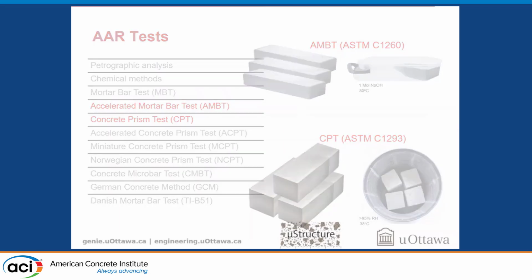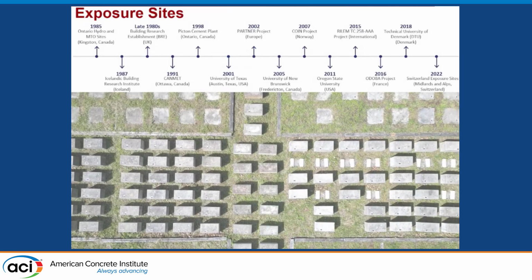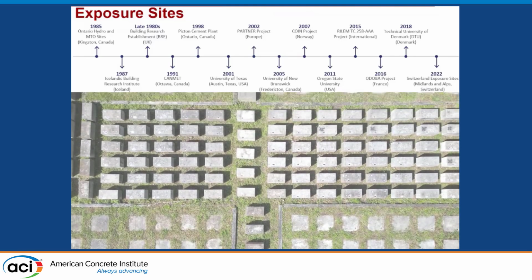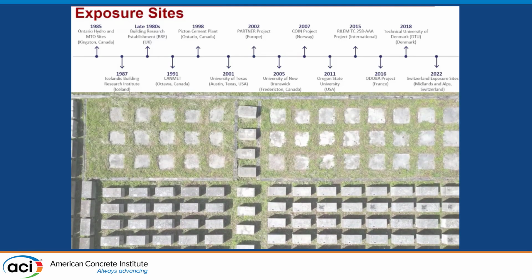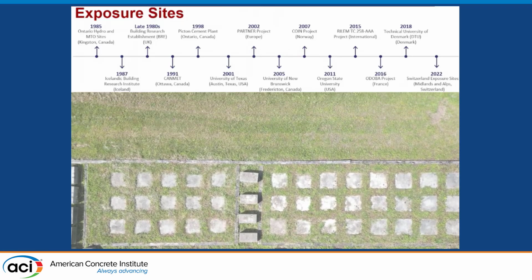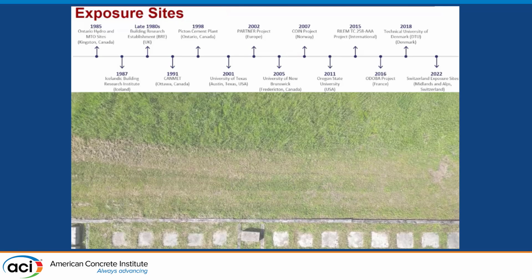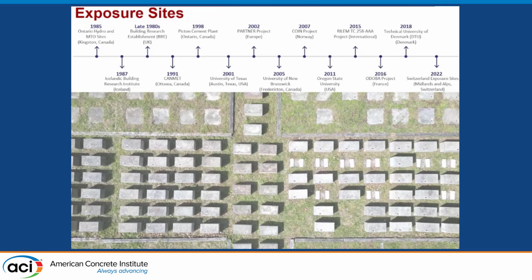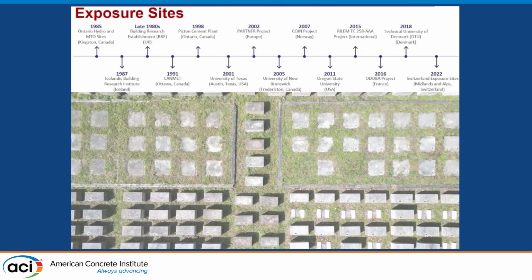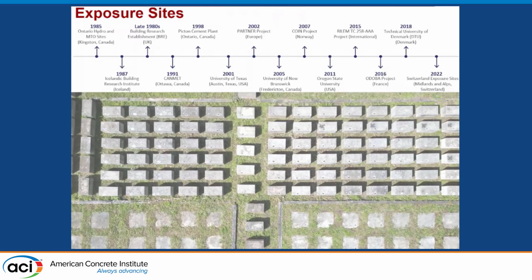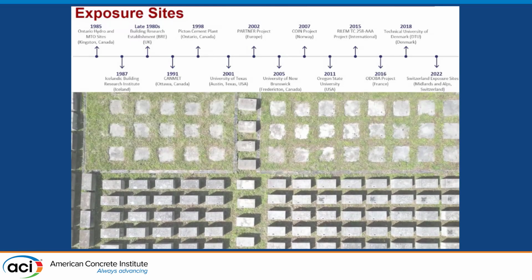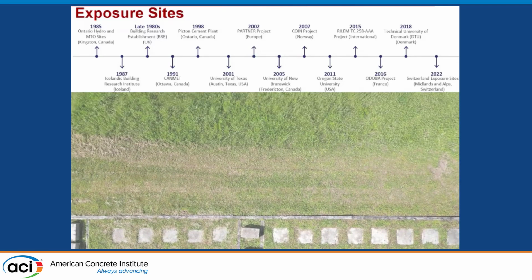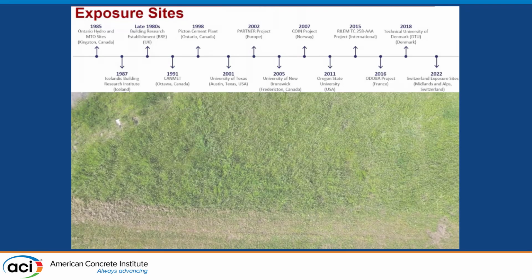So trying to understand what's going on under real exposure, several people in the world constructed exposure sites in which they expose blocks or slabs or beams, different types of structures, reinforced or not reinforced, and they measure expansion and deterioration over time. Several exposure sites have been built in North America, Europe, Asia, and so on, including one in Ottawa that was constructed by my former supervisor, Ben Fournier, in the early 90s, and it reached 30 years of measurements.